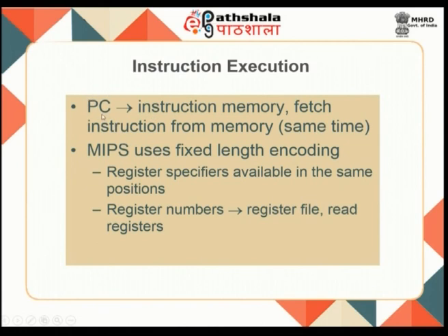You know, the program counter always has the address of the next instruction to be executed. So, use the program counter to address the instruction memory and fetch the instruction from memory. And in the case of your MIPS architecture, because all your instruction formats are of the same type, they have the same size, everything is a 32-bit instruction. To fetch an instruction, it takes the same amount of time.